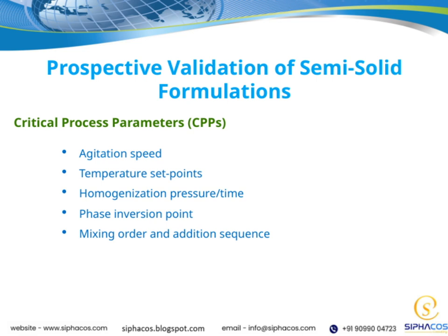The phase inversion point is another crucial concept. It marks the transition where the emulsion changes from oil in water to water in oil, which can significantly impact product performance. The mixing order and addition sequence are often underestimated, but are essential for controlling the formation and stability of our formulations. Proper sequencing can prevent issues like phase separation or incomplete mixing. All these factors tie into what we call critical process parameters, or CPPs, those variables we must control tightly to ensure quality.